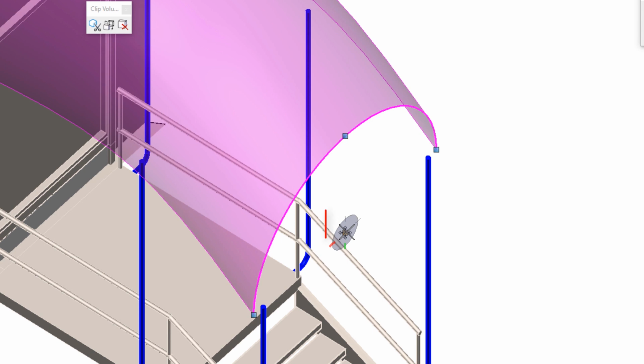Now what you're going to see on the screen is the AccuDraw compass appear. Its current orientation isn't the planar direction I want to move this arc. The direction I want to move, or the plane that I want to move on, an element in the file that represents that would be this point right down here, the top of this ledger. So I'm going to rotate the AccuDraw compass by using a shortcut. It's a 2-letter shortcut. The letters RE. So I'm going to type in RE.